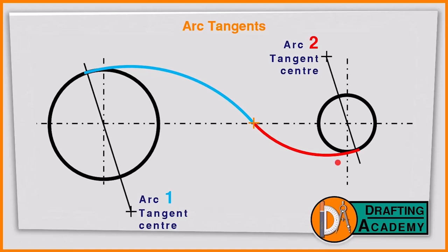What you see in this simple description about tangents is I'm trying to keep it as simple as possible and outlining the main concepts that you always need to make sure you have. Key things to remember about tangents is we have a normal, point of tangency, and the tangent itself. The tangents we're going to be drawing will be tangents to mostly circles, and whenever we're drawing them, we need to make sure we have drawn the normal before we can draw the tangent itself.